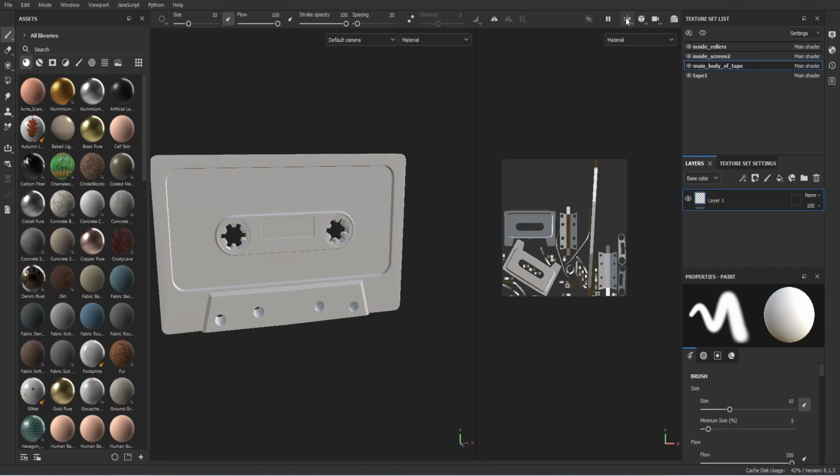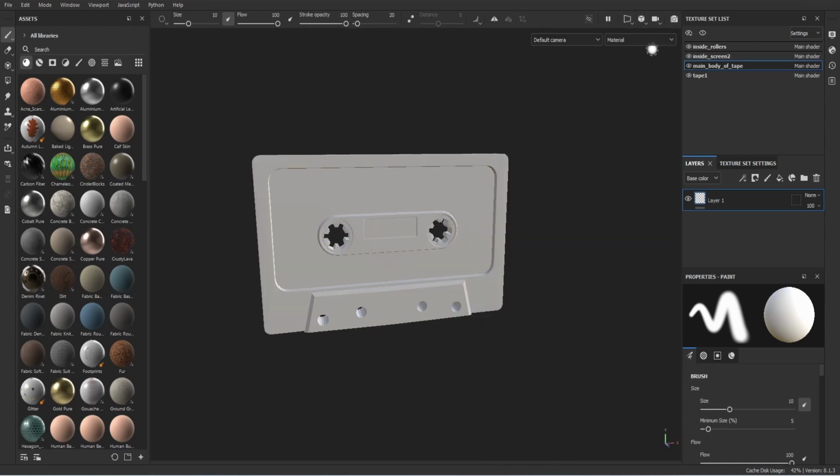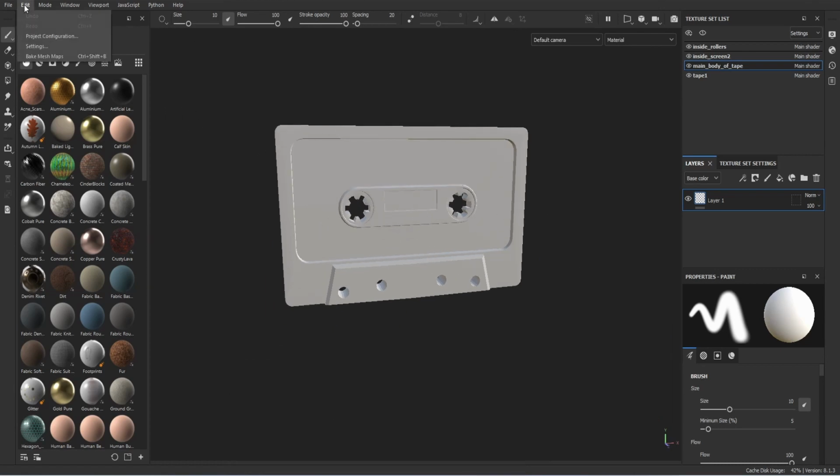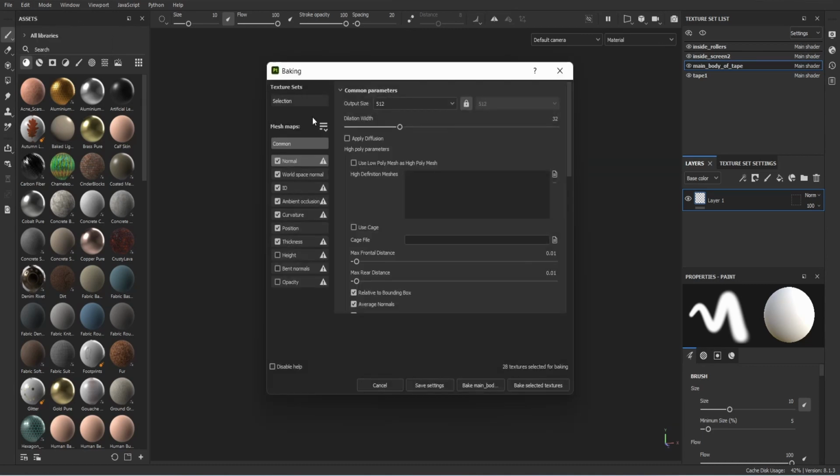You can always turn that off and on, so 3D, 2D, 3D only, 2D only. Typically go on 3D only so you've got more workspace. Now, once we're in, first thing we need to do is go to Edit, up here, Make Mesh Maps.